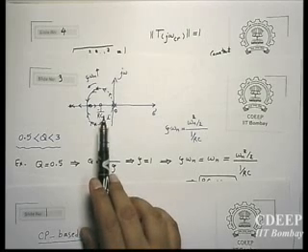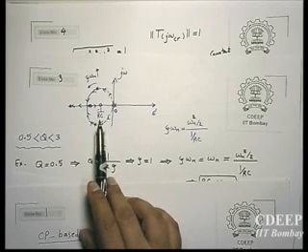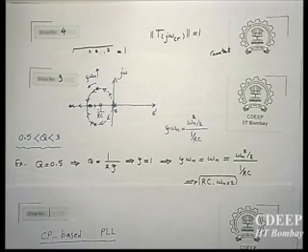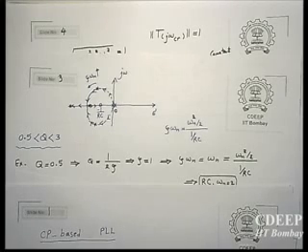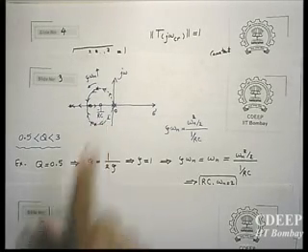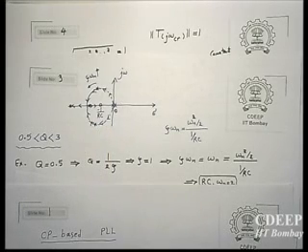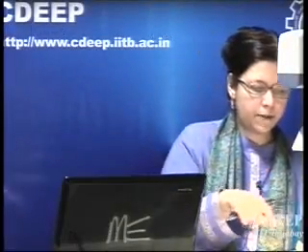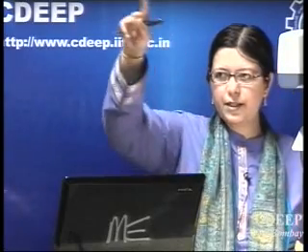Therefore you will see 0 and then pole. The kind of transfer function you will see will be a lead lag transfer function, because the magnitude of the 0 is smaller than the pole. Therefore you will see some kind of peaking in the closed loop transfer function just because of this.